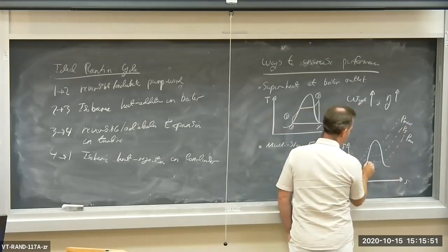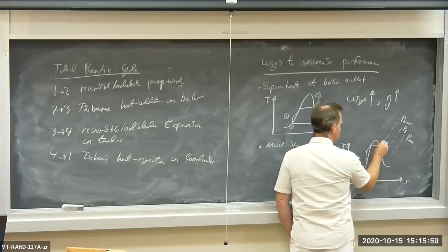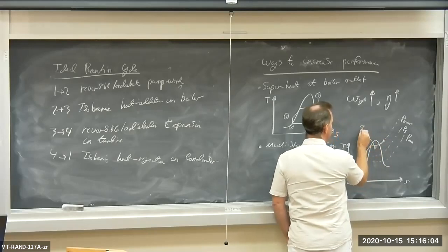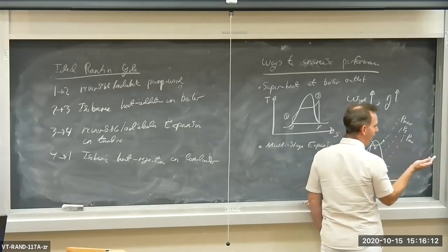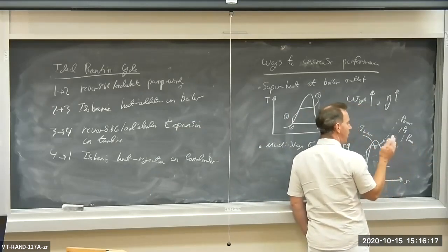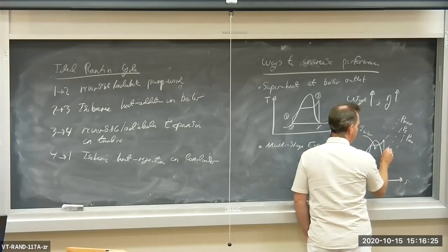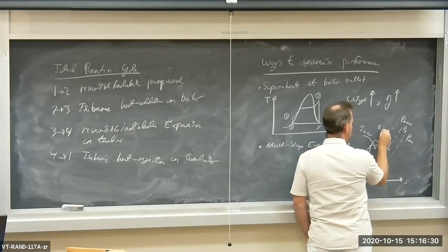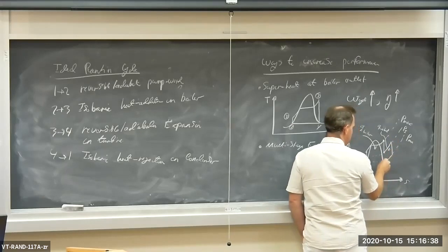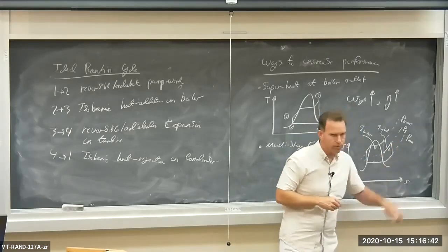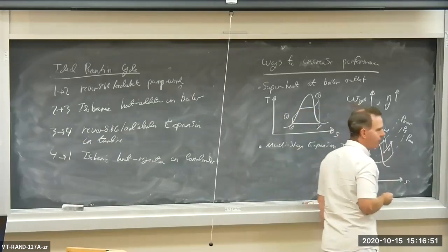So what we can do here is we can start off with reversible pump work all the way up to P max, add heat, superheat. So here's where Q boiler is right here. And then we can pass the H2O through a high pressure turbine, followed by a reheater, followed by a low pressure turbine. So we have expansion in the high pressure turbine. Then we have reheat. So we have Q reheat. And then we have further expansion. Maybe my diagram isn't the best here. I don't think we're going to end up quite as far out in the superheated vapor region here. But we can have multi-stage expansion in multiple turbines.